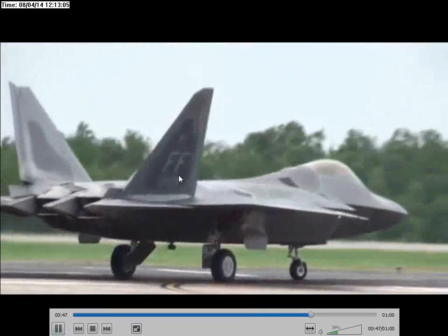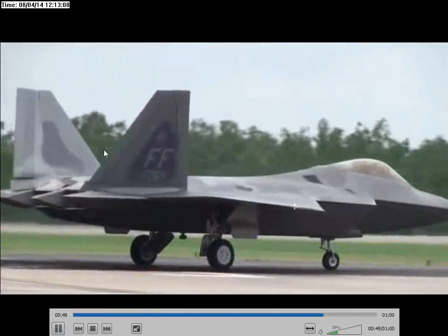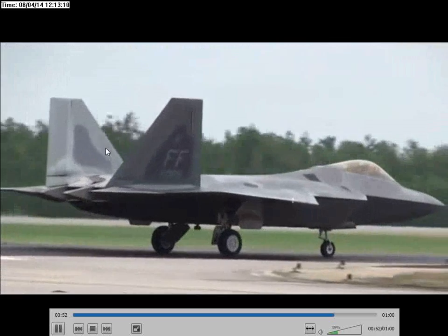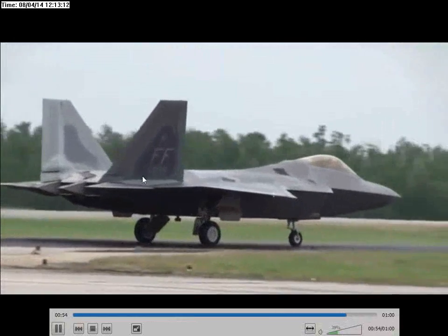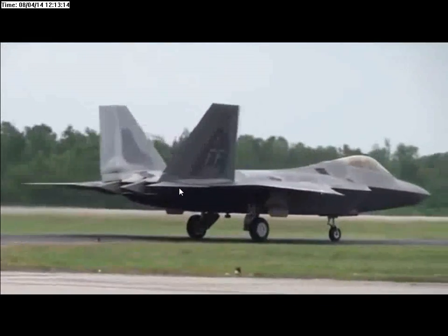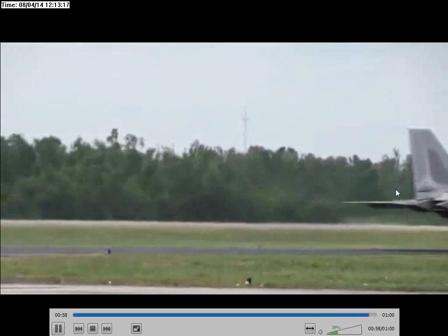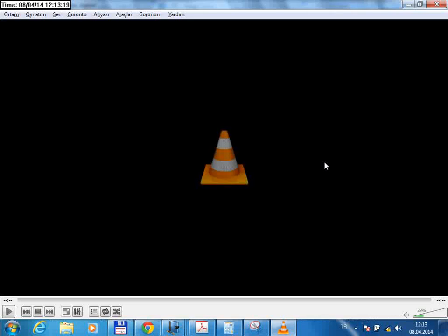And normally during regular flights the elevator will be providing the pitch control, but in the case of standing still in the air, then the elevator will be inoperable, and in that case the thrust vectoring will be providing the pitch control.